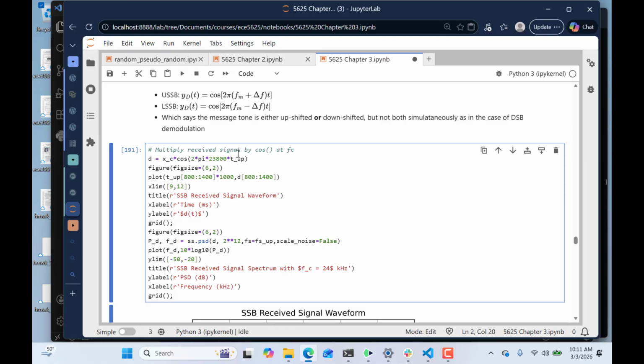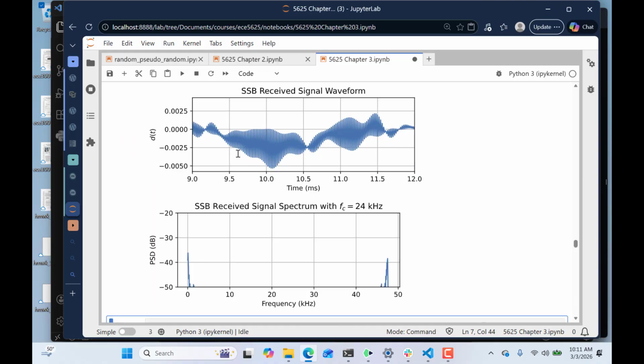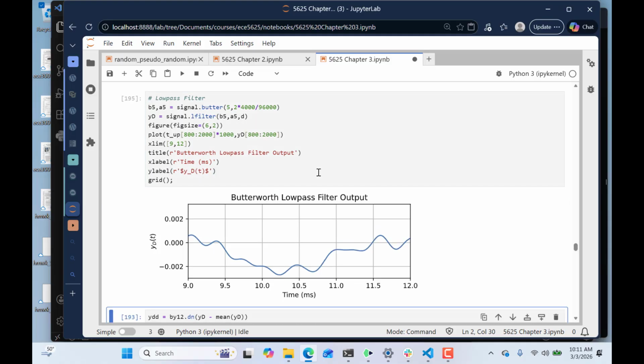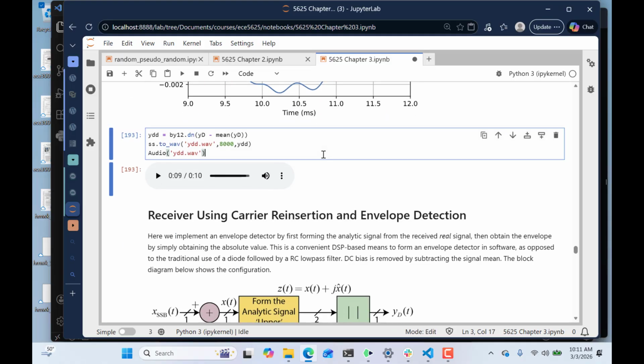This was the nature of single sideband in the early days. So what would happen if I shift it in the other direction? You might like this better. I could take this, shift it off by 300 hertz. This is the coherent part, shifted down to baseband. That's the double frequency, which the low-pass filter in here, which is a Butterworth low-pass filter, is getting rid of.